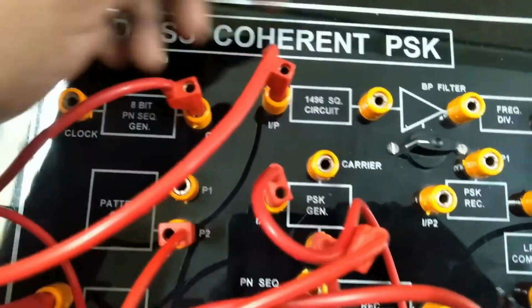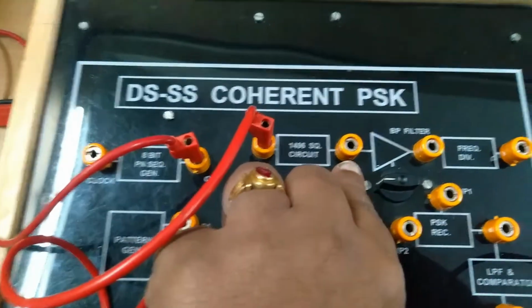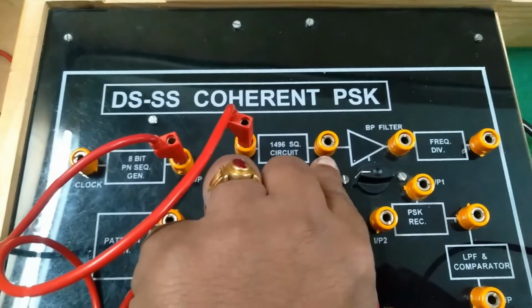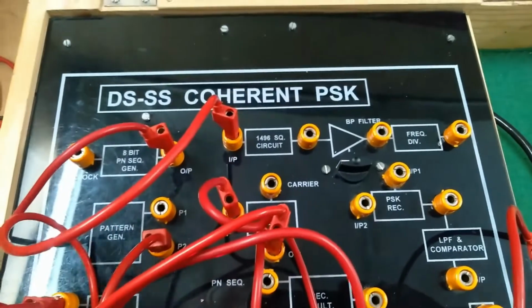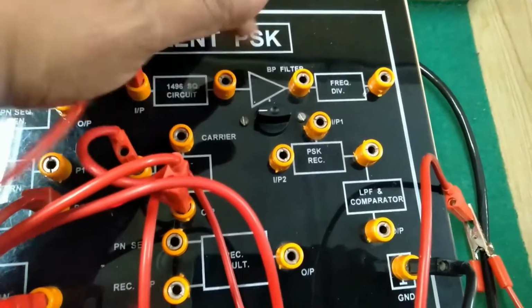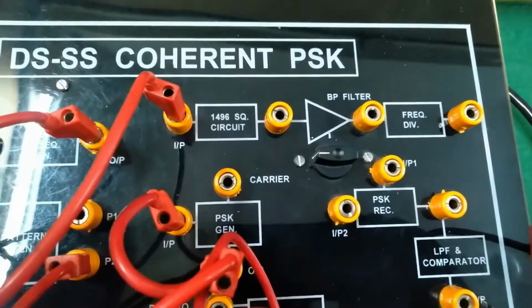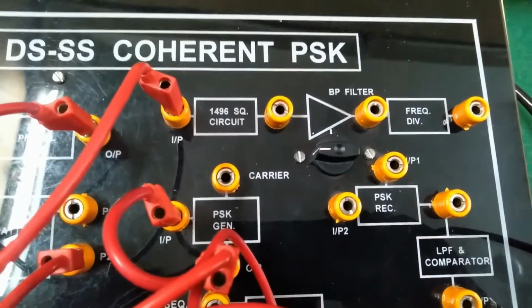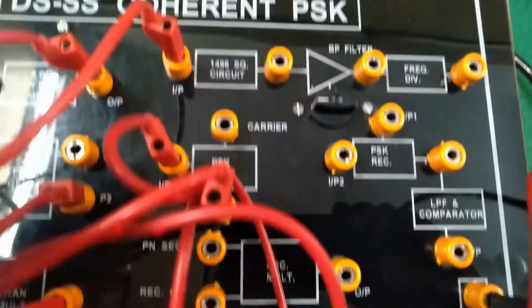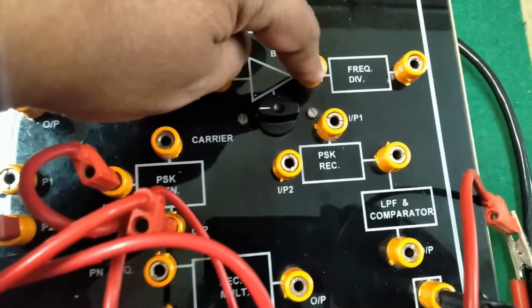So here you get sine square as 1 plus cos 2 omega ct. When you pass it to the band pass filter, the first component, 1, which is a constant DC component, will be attenuated by the filter, and only the cos 2 omega ct component will be there at the output of the band pass filter. So at the band pass filter, you are going to get twice the carrier frequency component.